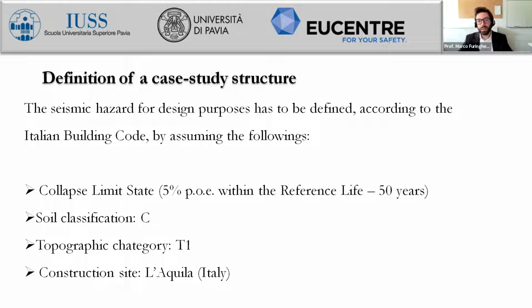And this is actually the key parameter according to which the seismic hazard is defined along the overall territory of Italy. Then we know, obviously, we need not only the peak ground acceleration, but also an estimation of the corner period and the ratio between the plateau spectral coordinate and the initial value at zero value of period. So these are the three main parameters that we need for the proper definition of the seismic hazard in terms of the response spectrum of acceleration values.